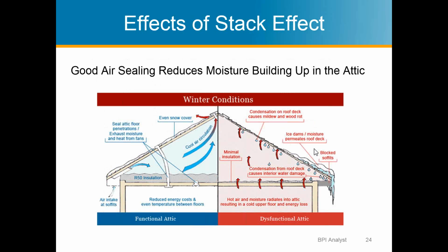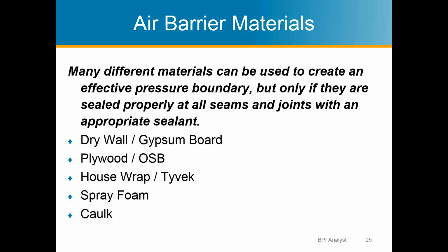And this kind of says the same thing. This is in a cold climate, and in a cold climate, say Lake Tahoe, you've got additional concerns. We're very fortunate in the Central Valley, where we have pretty low humidity and the temperatures don't get very low. But in a colder climate, air leaks can cause the vapor to condense on the roof and then freeze, and then you're going to cause additional problems, ice dams and stuff. But we don't have a lot of those in California, or at least not most of us.